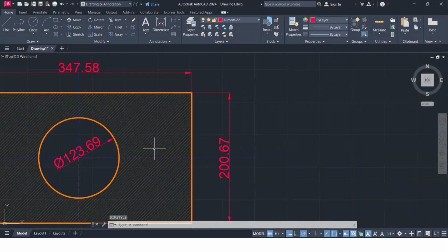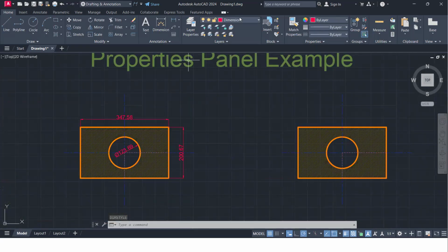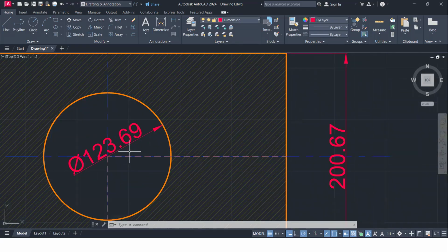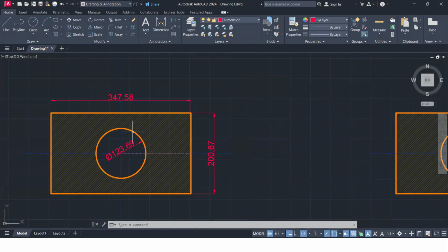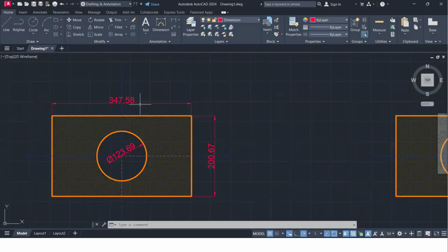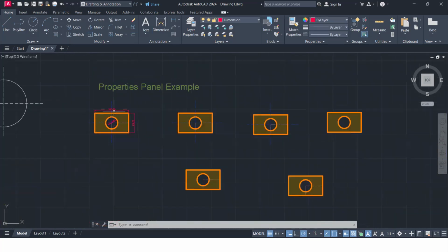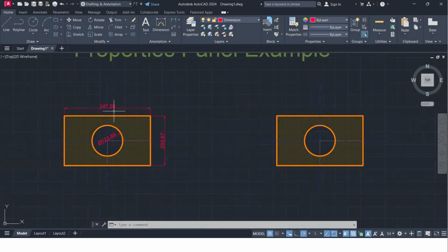And then what will happen? Because I selected my dimension there, whatever we change in the dimension style will occur in this portion also. Okay, this will change. My text and the size of the dimension increase, and all the colors. You can also change your colors, dimension type, anything you can change by yourself by use of this. It is not necessary to use this directly. Okay, anything you can do here.